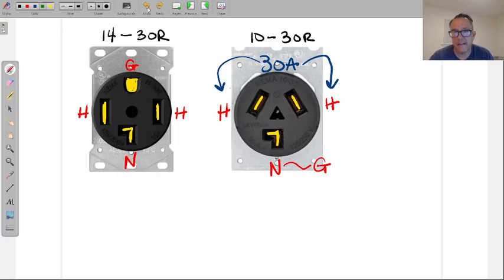It's grandfathered in. Now, if this was new construction, then no. You have to run the 4 wires and use the 4-wire plug, 4-wire receptacle. But I'm not going to tear out all this wire from the drywall, and then this is now a $1,000 job.